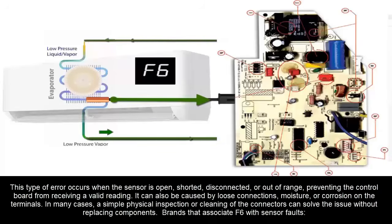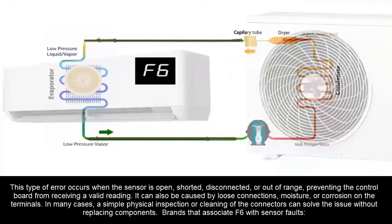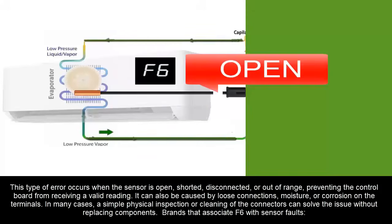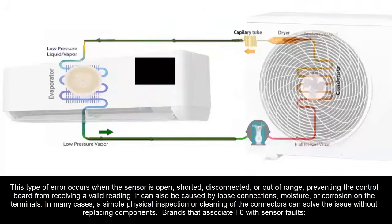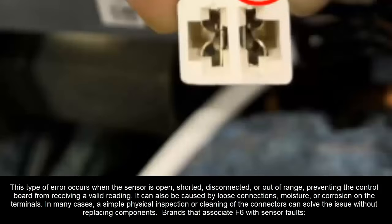This type of error occurs when the sensor is open, shorted, disconnected, or out of range, preventing the control board from receiving a valid reading. It can also be caused by loose connections, moisture, or corrosion on the terminals. In many cases, a simple physical inspection or cleaning of the connectors can solve the issue without replacing components.